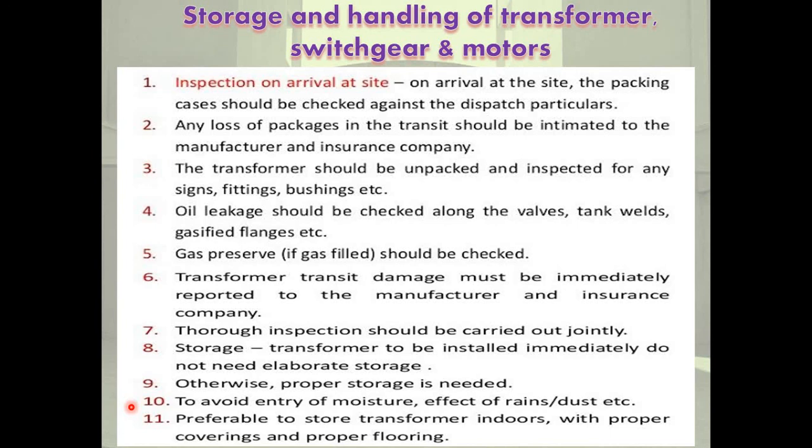Now, the static load and dynamic load of a running machine is transmitted to the ground via the machine's foundations. So, the procedure of the foundation of electrical machines. The 3 basic requirements of the machine's foundations are horizontal level, rigidity, and freedom from vibrations.